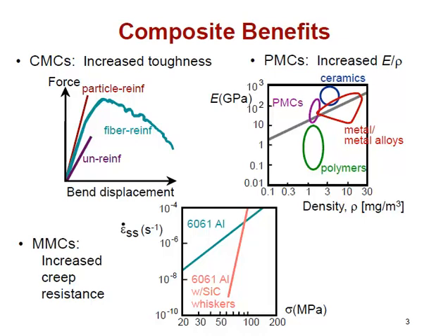You might still have a crack slowly propagating through the material, but it has to change direction every time it hits one of those particle reinforcers because it's difficult for a crack to cleave those. So this is fairly akin to the idea of a dislocation having to move around a dispersion strengthener, except this time it's a crack. And the more times a crack changes direction, the more surface area that it has to liberate and the more energy that is required to keep it propagating.